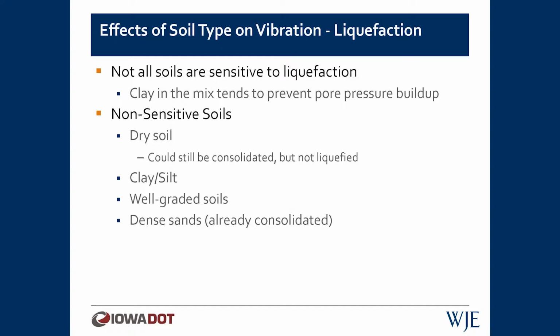Clay and silt is generally considered not liquefiable, because pore water pressures can't really build up in a clay. Well-graded soils, which gets back to the idea of adding clay to the mix. Essentially, it's been identified that uniform grain distribution is needed to lead to liquefaction. Dense sands are not as susceptible because they are already pretty well consolidated. They don't have as much water available in them if they're saturated.